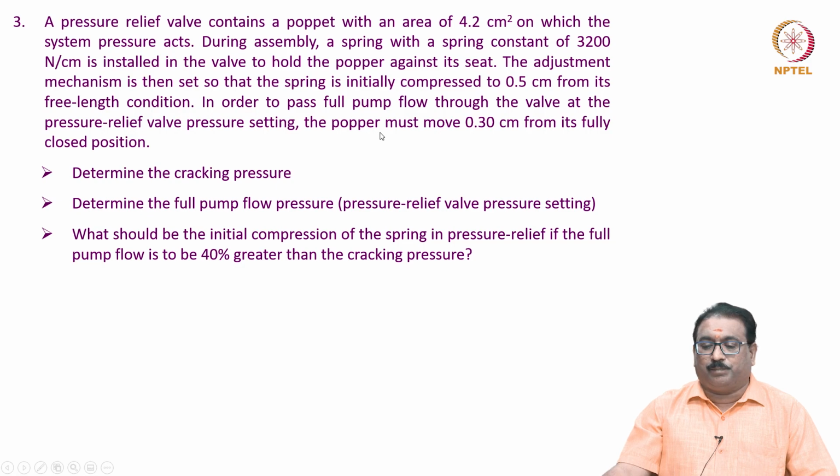the poppet must move 0.30 centimeter from its fully closed position. Determine the cracking pressure, determine the full pump flow pressure, meaning it is a pressure relief valve setting.